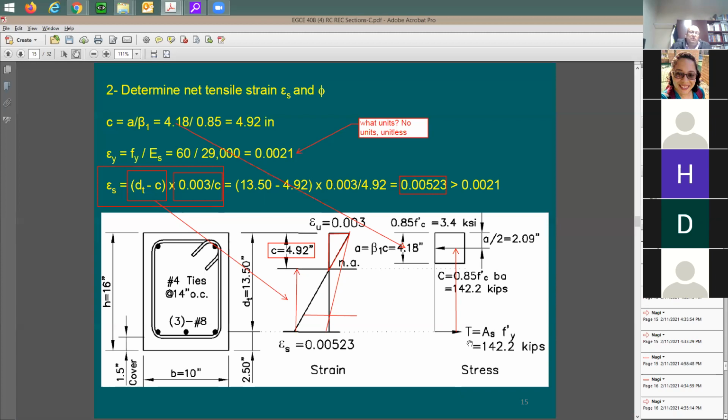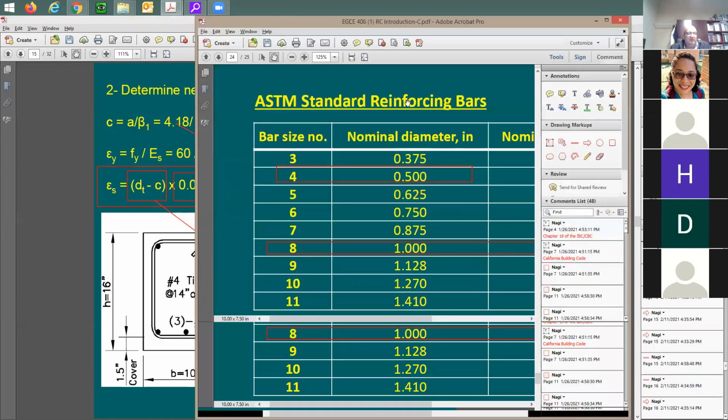When you reduce the force on the rebar, the strain also is going to be reducing, right? You're going to have much less force, much less stress, much less strain in the rebar itself. And when the strain in the steel is reducing, you're not going to have any yielding. Yielding is not going to happen.